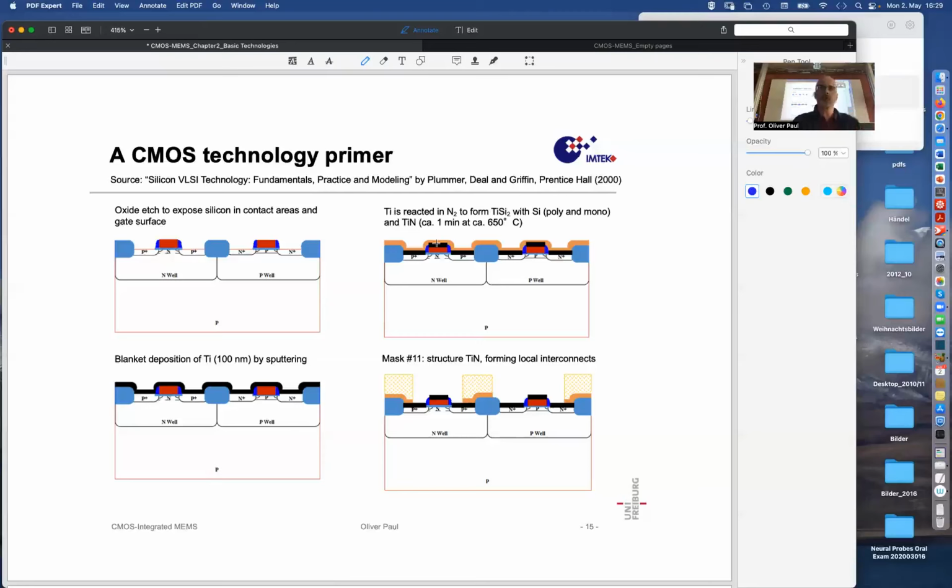The voltage needs to go there, and that has to do with, of course, the typical time constants. The typical time constant tau for an electrical signal with a resistor to assume a stable condition once some conditions have changed is RC. This is the time constant. Whenever you have a resistor in connection with capacitors, if your R is high, your time constant is going to be high. Now, where are the capacitors?